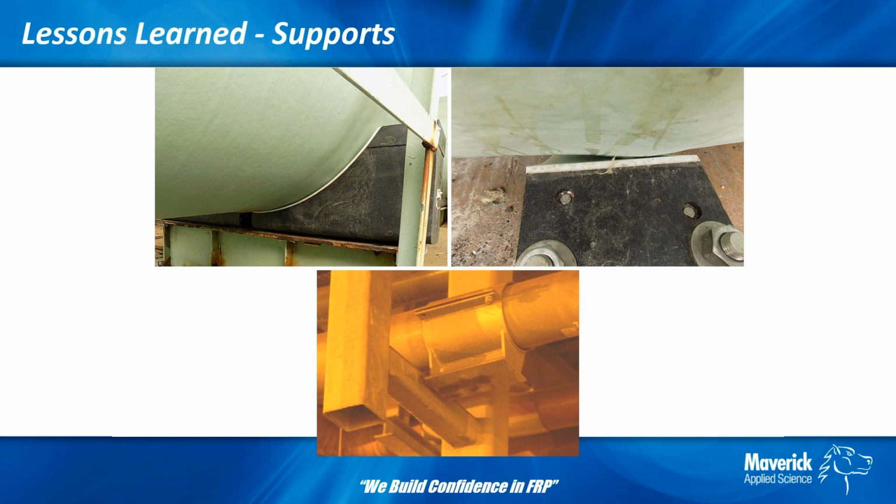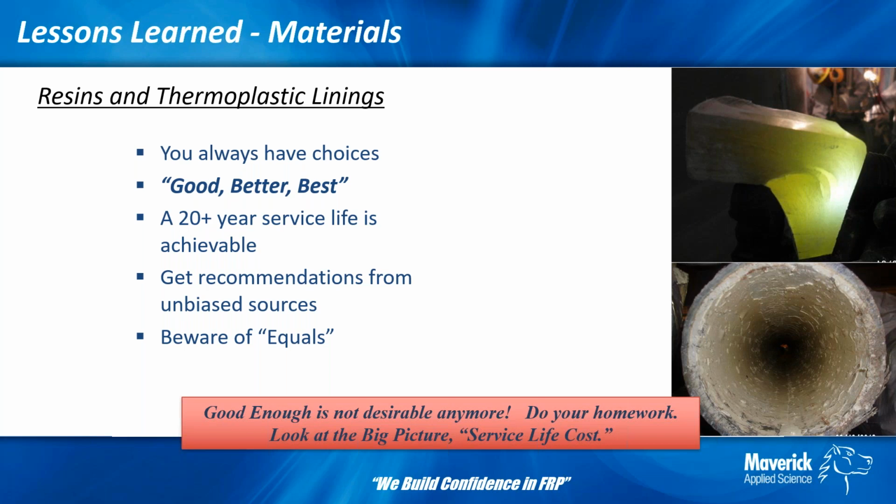And then the support at the bottom, you see, it looks like a pretty good support, but it's rode off the steel. Well, this is what happens when you don't analyze a system and you have basically uncontrolled, unpredictable thermal expansion, where over time the pipe moves back and forth, and that support slowly inches off the steel. And now the support is actually just acting as an extra load on the pipe, and the pipe is either unsupported at that point at all, or it's sitting on the steel. Either way, it's pretty bad. So this is another case where you really want to look at pipe stress analysis.